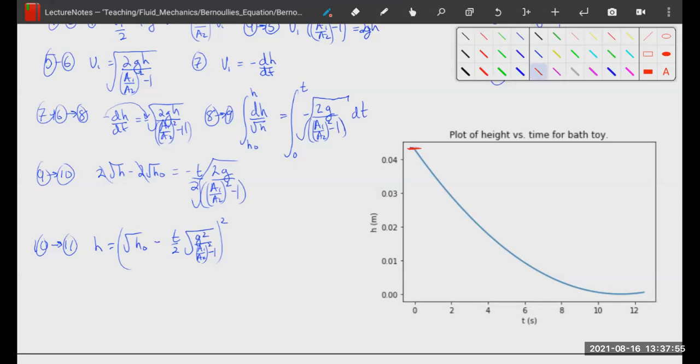So, fun things about that video. One is that it's very easy to tell when the liquid starts flowing. It's quite difficult to tell when it stops flowing, and that's because of one of the limitations of our model. Our model does not include surface tension, right? So at the end, when it starts dribbling, it goes drip, drip, drop, drop, and it's unclear exactly when it stops flowing because of the pressure effects due to surface tension.